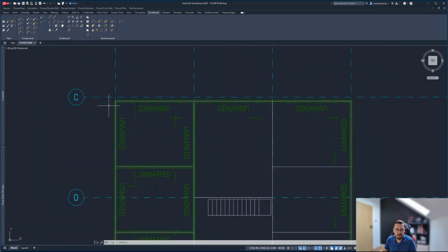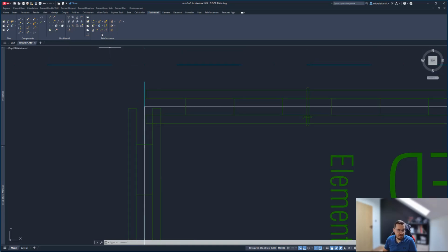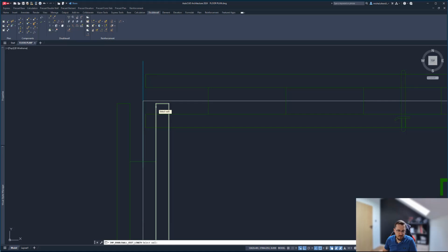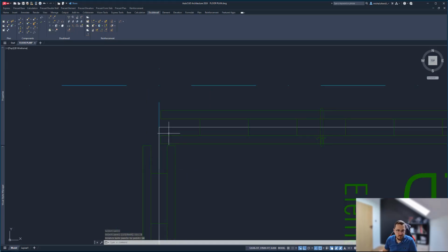Okay, those panels are on top, so let's do that. I can now easily edit the length of the panels. There is an option here available, which will allow me to edit the panel lengths. So let's do that for this. Now, let's actually edit both panels. Move it here, and let's actually move that again, both panels. What I'll do here is just move that 10 millimeters, so we have the nice spacing. And you can see that the girders move as well.